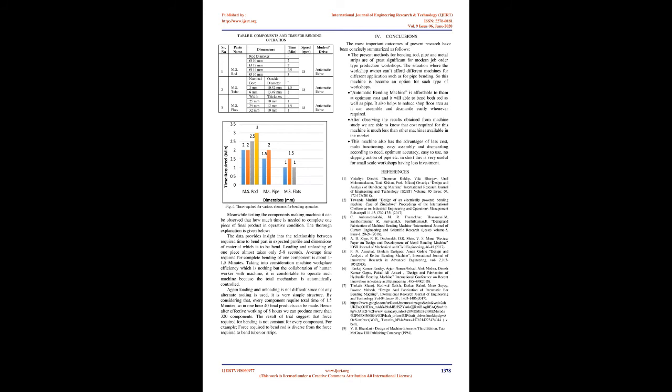The thorough explanation is given below. The data provides insight into the relationship between the required time to bend a part in the expected profile and the dimensions of the material which is to be bent. Loading and unloading of one piece takes only 5 to 8 seconds. The average time required for complete bending of one component is about 1 to 1.5 minutes.